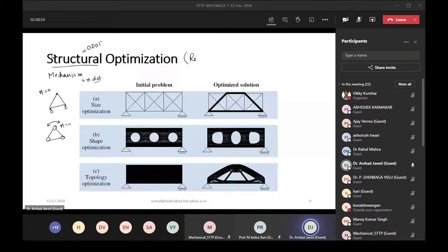Contrary to this, if you take 4 joints like this, and fix these two, you will find that there is a large motion because the degree of freedom is 1. So there is not much difference. The structure is the same, joints and links are the same. Only the numbers are going to change, which gives different degrees of freedom.